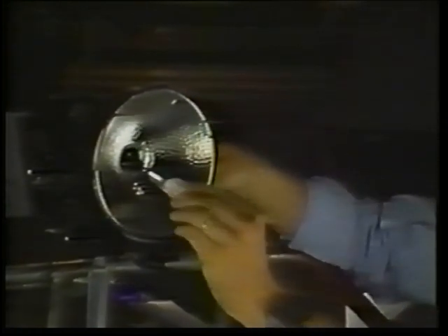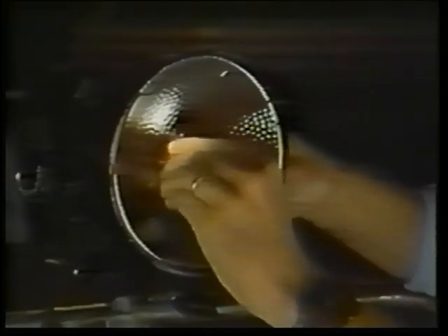It's important to note a tungsten halogen lamp should never be touched with your bare hands. Skin oils can contaminate the high-purity quartz and will reduce lamp life. One recent innovation is the MR16, or True Aim lamp. The MR16 consists of a small tungsten halogen capsule in 20 to 75 watts, mounted in a multifaceted reflector.